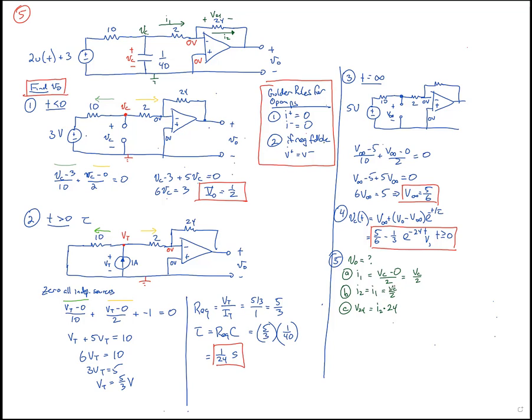And interestingly enough, we already found what I2 is. It's equal to VC over 2. So just substituting in what I2 we already found, that whole thing is equal to 12 times VC. So if we knew what VC is, and we already found it here, multiplying it by 12 tells us what the voltage is across this. And that's really close to the voltage at V naught.